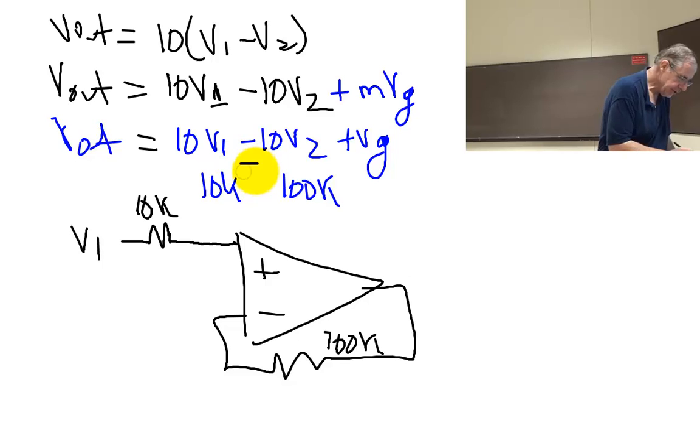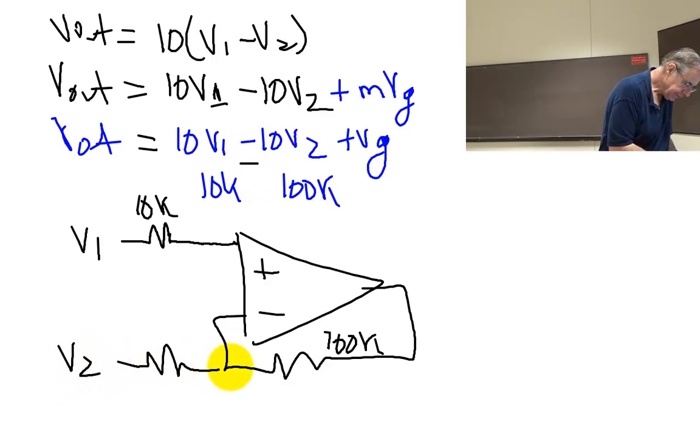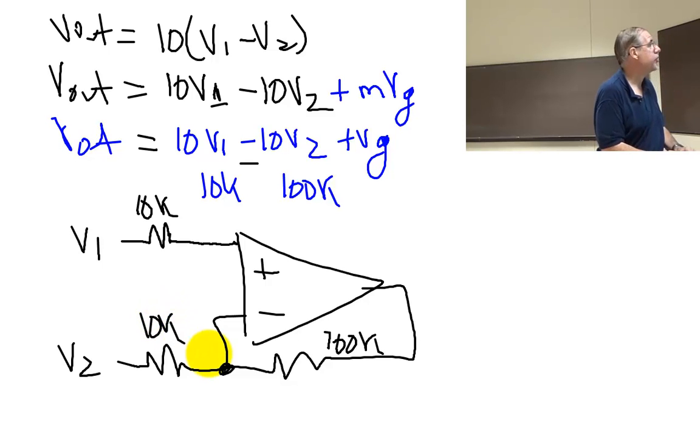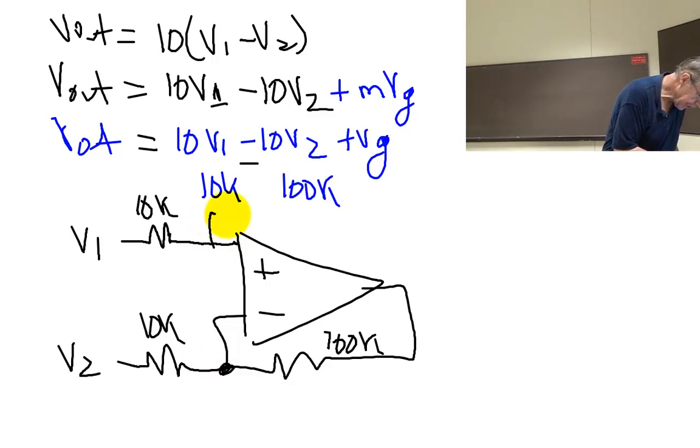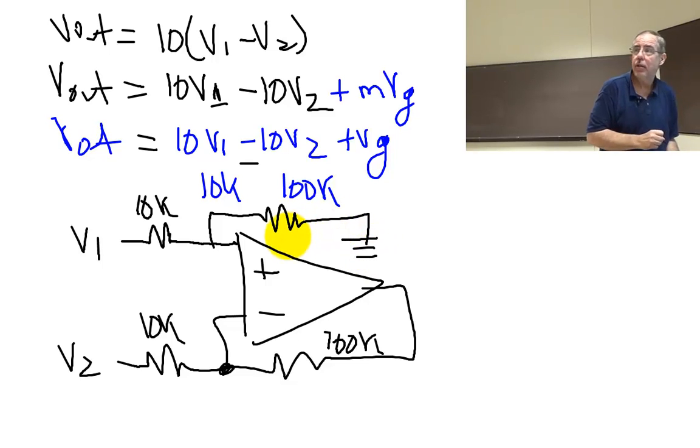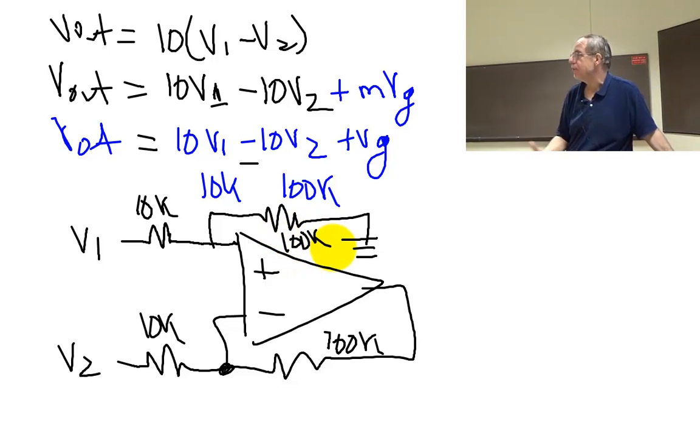All right. What about V2? It's negative, right? You see that? Negative. And it needs a ratio of 10. But got one more, right? VG. And it's positive. So it goes into the positive side. And just to make it look exactly like the circuit that I drew earlier. But what value goes there? 100. Does that look familiar? That's the standard differential amplifier we had before. We don't ever use this one because it's really crappy. It has bad input impedance.